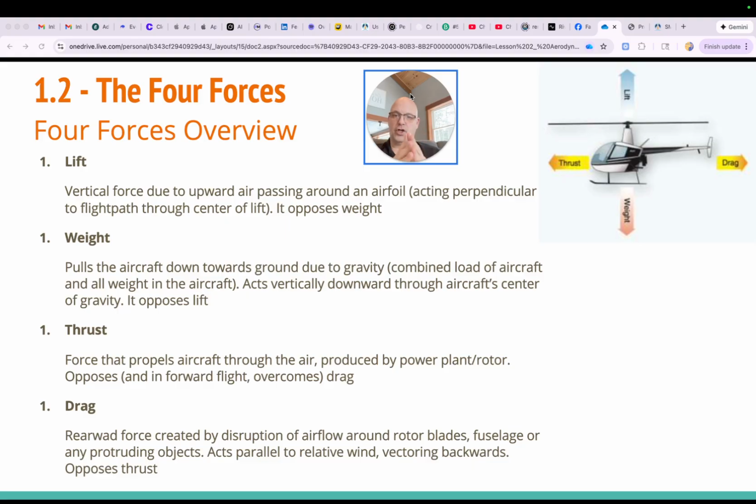And of course, it starts with a good pre-flight. It starts with making sure that you do a weight and balance on your aircraft itself to make sure that your center of gravity is in the right spot, within the safety envelope. Now, as you continue flight for the hour or two, that will shift a little bit because of fuel changes, but also the total weight, that you have to make sure you don't stress out.